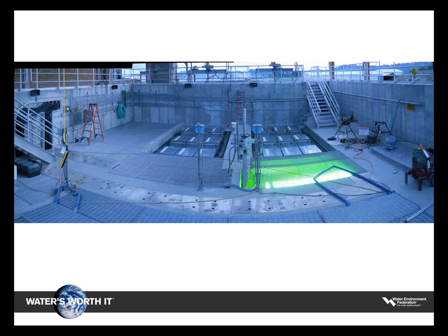Ordinarily, our suspended solids and our BODs here over the course of this plant averaged 5 milligrams per liter per month. We ran it all the way up to 35 and even 40 at one point just to make sure that if something disastrous happened, we would still get disinfection that would meet our state permits, and we did get that done.